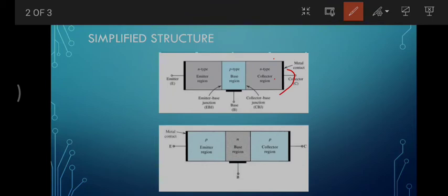Another transistor, a dual of the NPN, is also shown, which has a p-type emitter, here you can see, an n-type base, and we can also see a p-type collector. Such types of transistors are called PNP transistors. A terminal is connected to each of the three semiconductor regions of the transistor, with the terminals labeled emitter with E, base with B and collector with C.